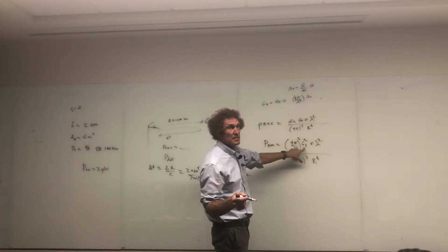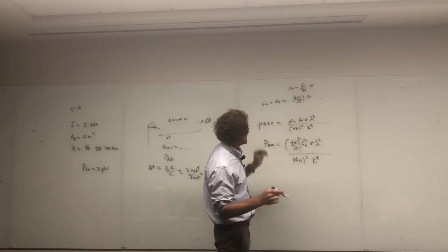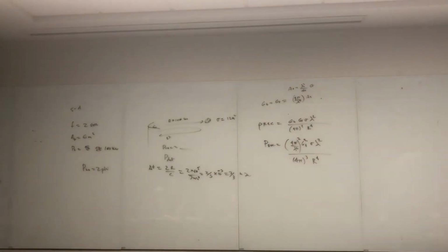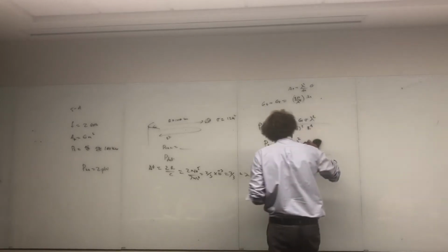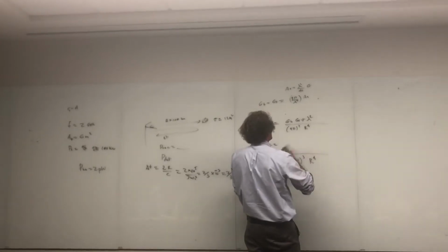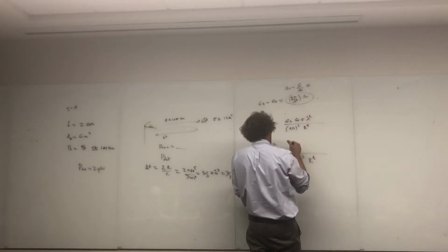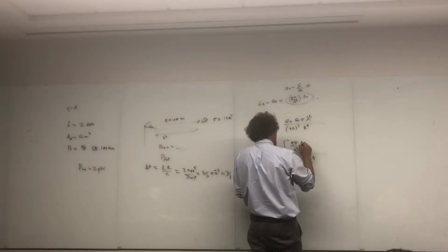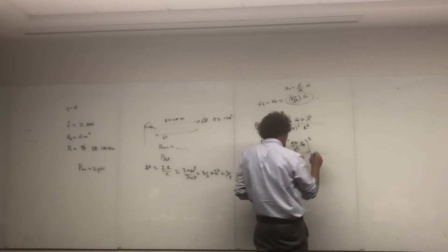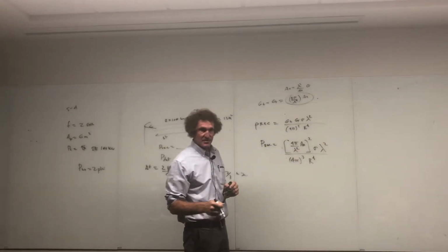Yes. But I think that gain transmitter should be area. Wait a second. Oh, I'm sorry. You're absolutely right. It's been one of them days today. Let me put it the way I should say it. Since this area is given, I should just put quantity 4 pi over lambda squared times the effective area, squared, times sigma times lambda squared. There. I apologize for that.